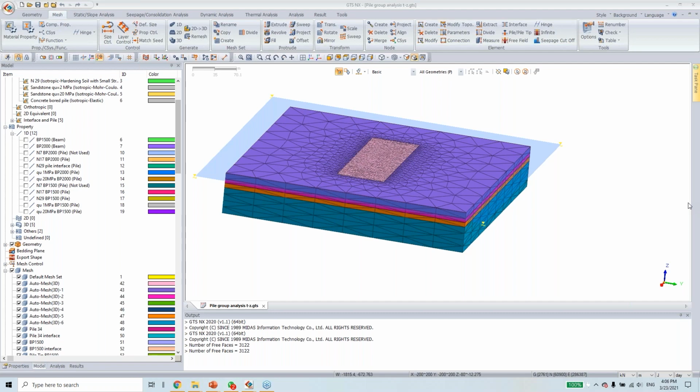The difference is just that in fully coupled effective stress analysis, you combine the seepage and the stress analysis into one, and you have to define the time steps for the excavations. How we model the water flow is we fix the water table at the far end, around the boundaries, and we define the zero pore pressure at the base of excavations, and let the program calculate the water table for you.